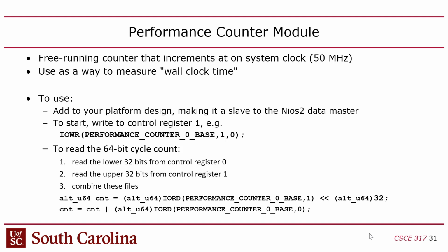So obviously, it's going to take multiple operations to formulate a 64-bit value. Also, the Avalon bus is only 32 bits. So you have to essentially read the lower 32 bits and then the upper 32 bits and then concatenate them together. But the concatenation is only in software, because the registers are still 32 bits in the processor, right? You guys with me? And that's how you do it.